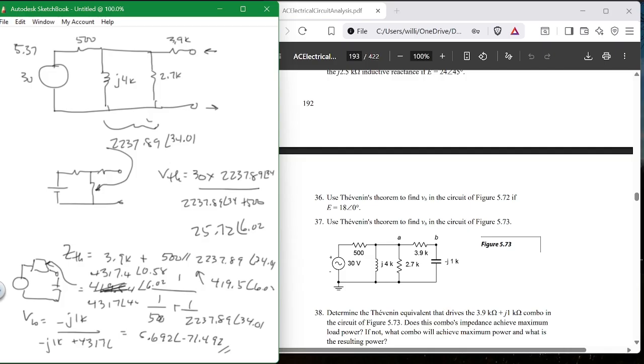Here again, you do the same thing you did in number 4. You use the magnitude, because they put such a high resistor there for R, you can ignore the reactance of the inductor.